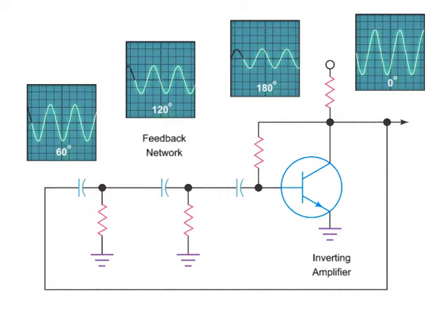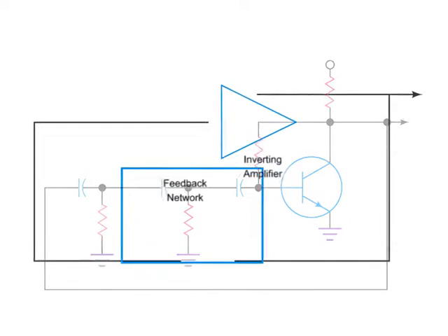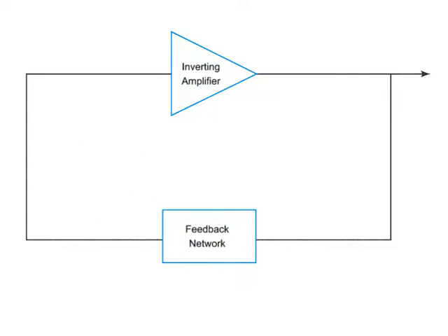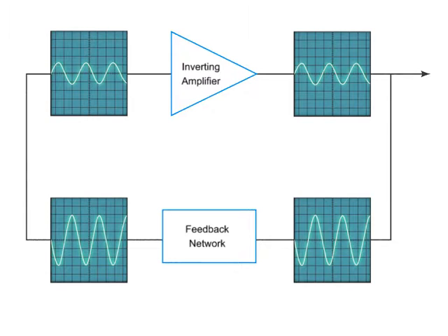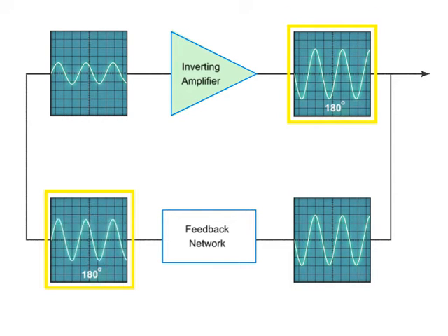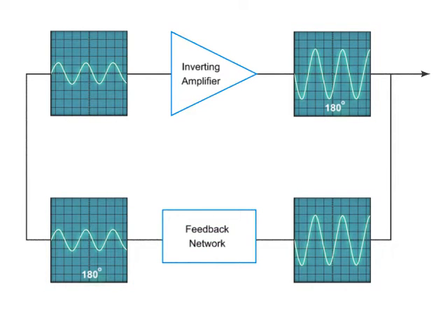In order for the oscillator to produce a repetitive oscillating electrical signal, it must follow two criteria. The circuit must have a loop gain that is greater than 1, and it must maintain its phase state. The phase state is sustained when the inverting amplifier's 180 degree phase shift is reversed by the 180 degree phase shift of the feedback network. Thus, maintaining the phase state is accomplished by a 360 degree change in the phase as a result of the 180 degree signal inversion at both the inverting amplifier and the phase shift network.